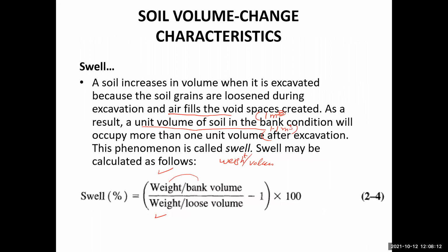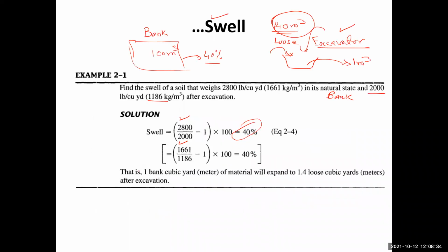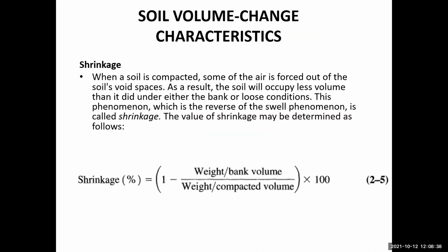So based on these properties, we have certain characteristics of the soil. Swell means when the soil is removed from the bank condition, the soil expands. That expansion of the soil is called the swell, and that swell is measured in terms of percentage. And we did one example for the swell as well.